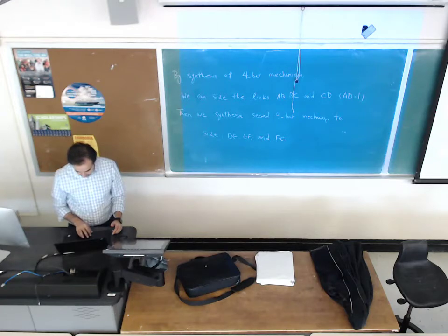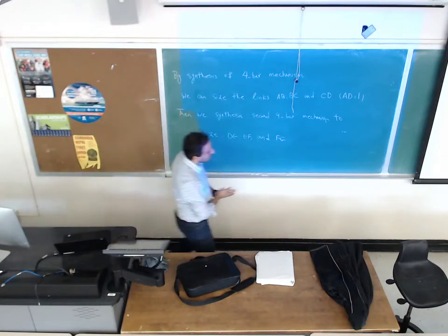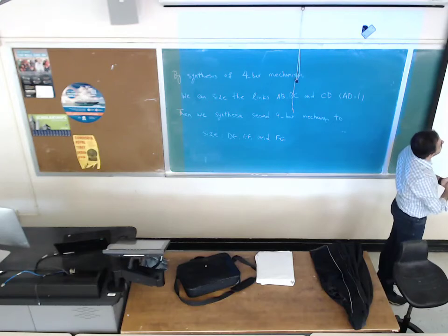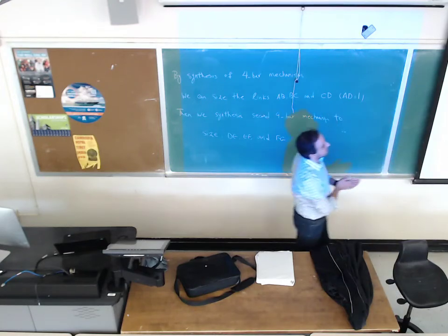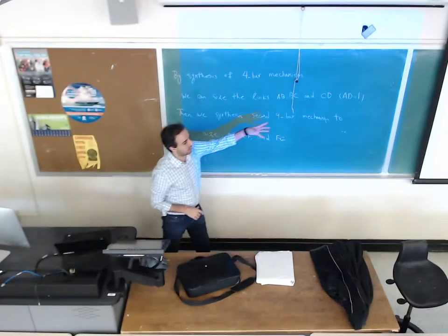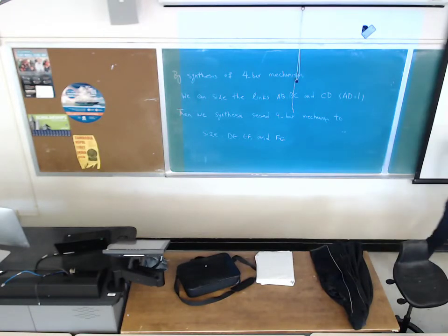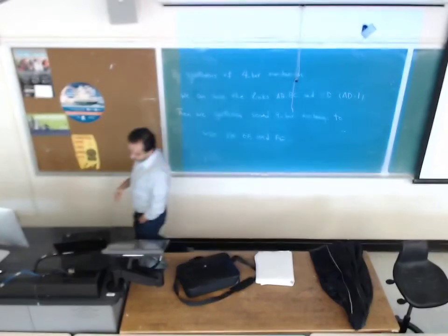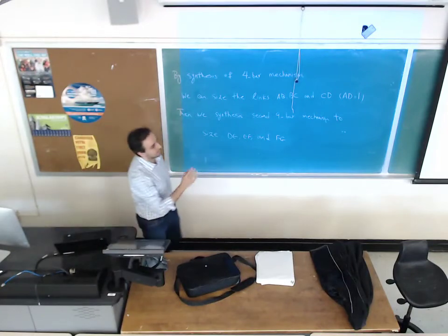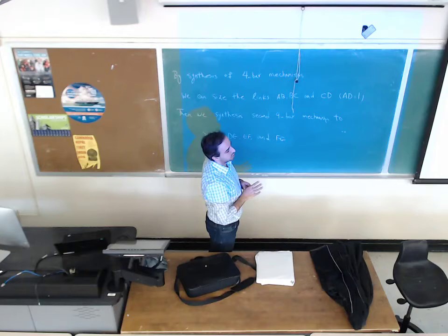Least square method. When we started kinematic synthesis, we talked about the precision point, and we looked at this table. The table says if you have a function generation problem for a 4-bar mechanism, the maximum number of precision points that you might have is 7. So you can have up to 7 precision points to design a 4-bar mechanism such that it generates those precision points for you.